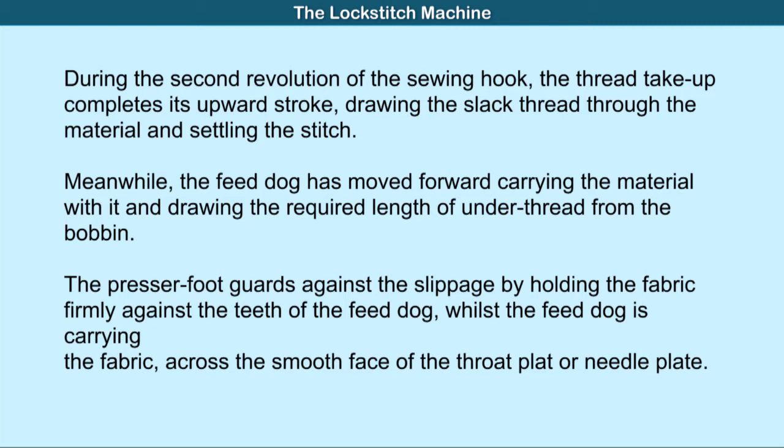Meanwhile, the feed dog has moved forward, carrying the material with it and drawing the required length of under thread from the bobbin.